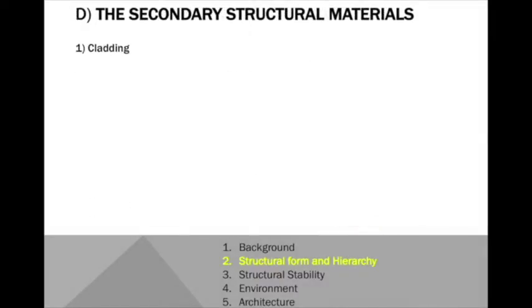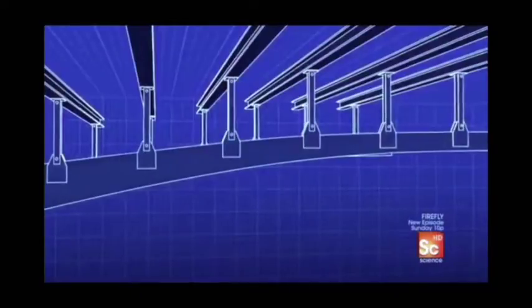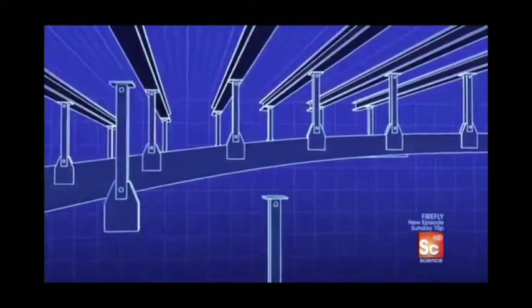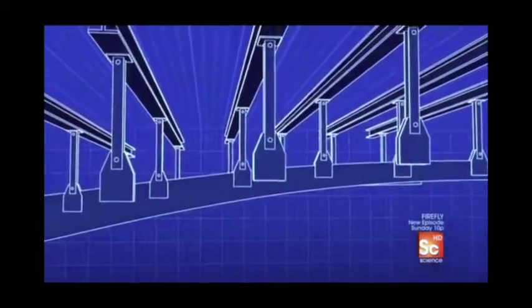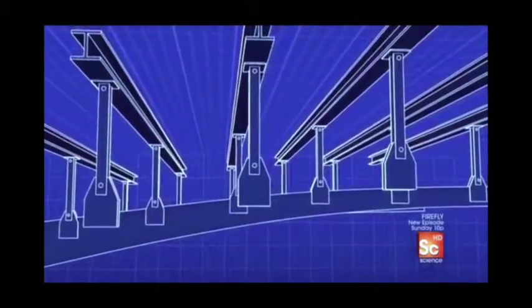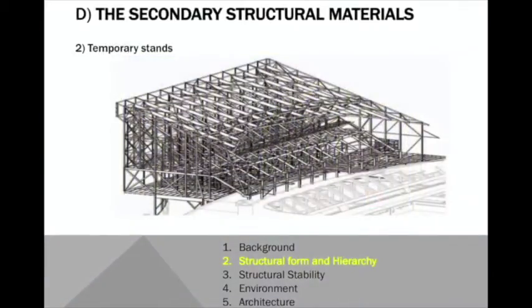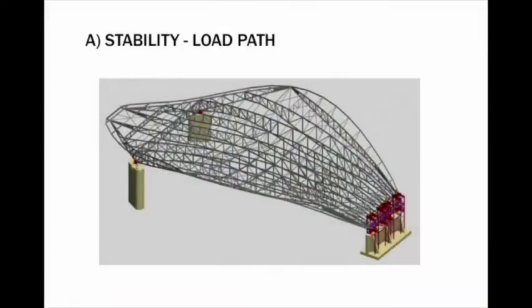Also, the roof structure is fully clad in aluminum and features a timber soffit to its underside. Because aluminum can resist corrosion more than steel, it's a lot lighter in weight, which decreases the load on the truss over the long spans, and also because it looks better. The final structure comprises braced steel frames made out of standard universal beam and universal column sections, with all bolted connections to enable repeat erection and later disassembly. There is a clear load path. The load applied on the roof will be transferred through the trusses to the concrete supports and then to the foundation on the ground.